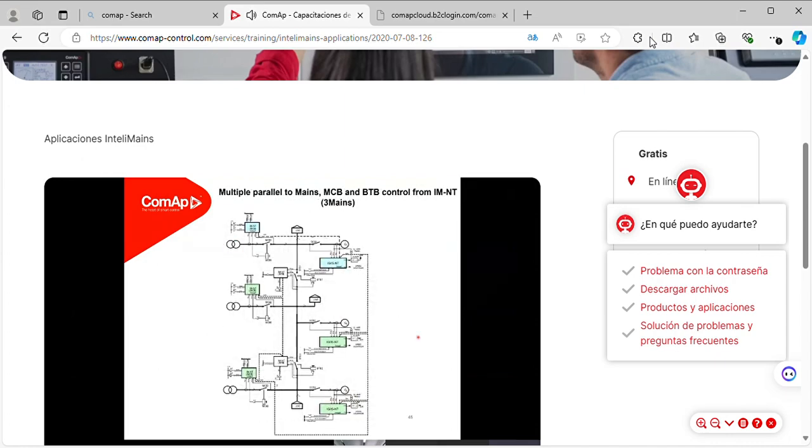You can go for multiple utility again, so we can further subcluster them. So 3 utility systems on the left hand bank, and there are 3 clusters of gensets on the right bank, and in between you can think of multiple bus ties to isolate individual groups. So the top half is one group. This is your second group in between with MCB2 and genset 2, and the last one is MCB3 and genset 3. So this is 3 groups, and in between these bus tie breakers allow you to cluster, say, genset 2 to genset 3 or genset 2 to genset 1, or even if you close all the bus ties, G1, G2, G3 can synchronize between them as well.